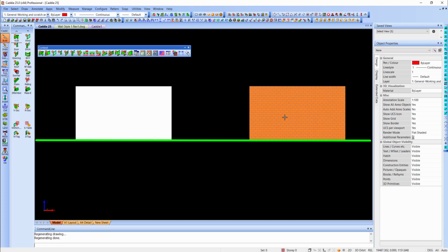So whatever resides below this level will not be displayed by default unless we go and change it. You might think that this is a bit stupid. Well, the reason behind this is that you can draw your whole structure without displaying the foundation. Only the objects involved in a section where you want to see the detail below this level, for these ones you can adjust the cut line. I will show you how simple this really is. It sounds complicated, but it is not.